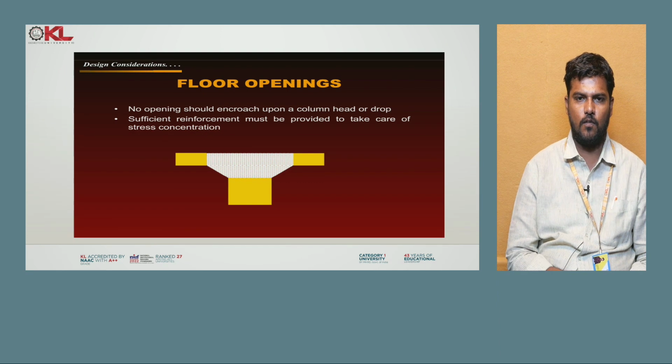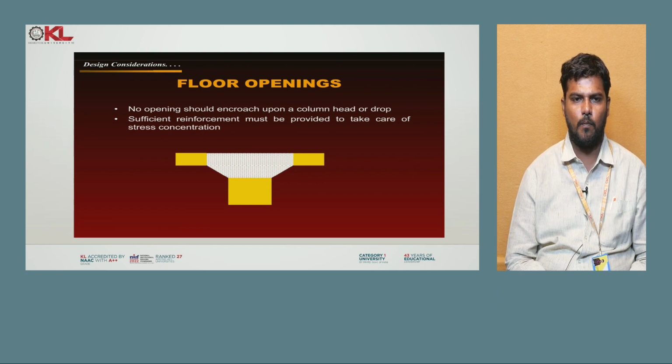Next one is about the floor openings. No opening should encroach upon a column head or a drop. Sufficient reinforcement must be provided to take care of the stress concentration while making the floor openings.